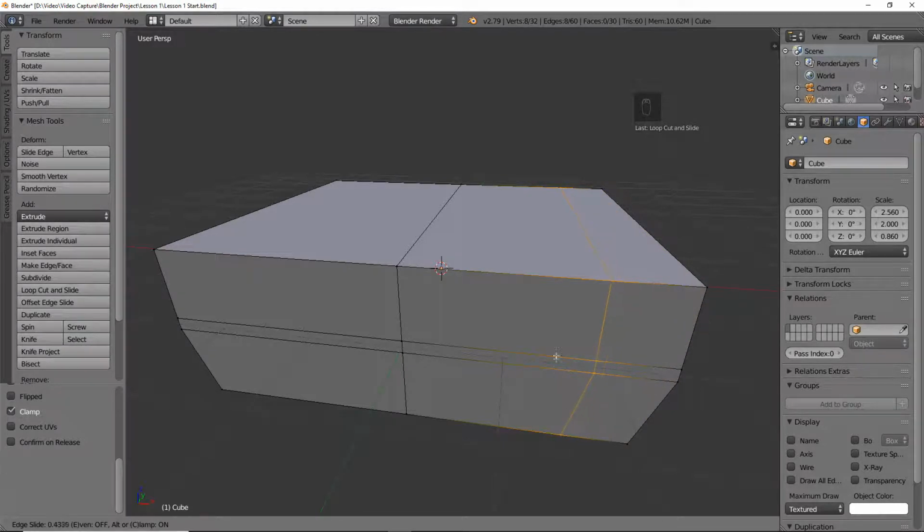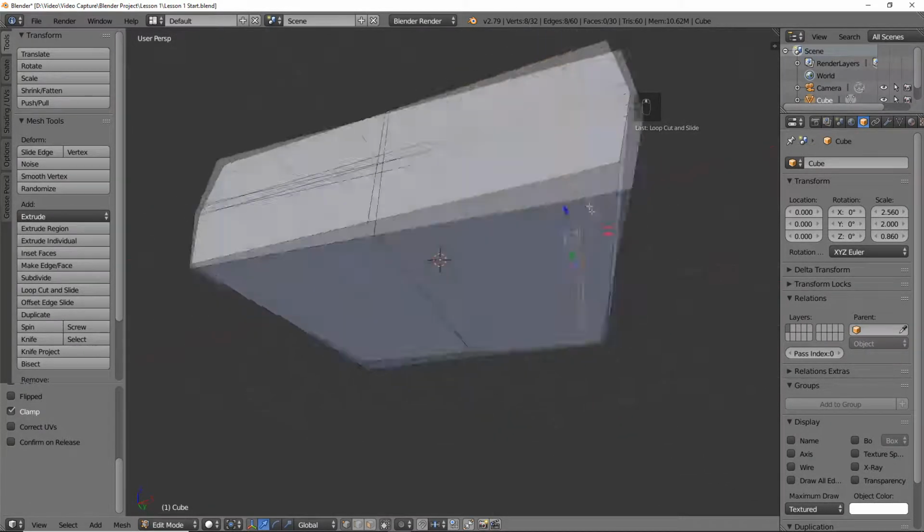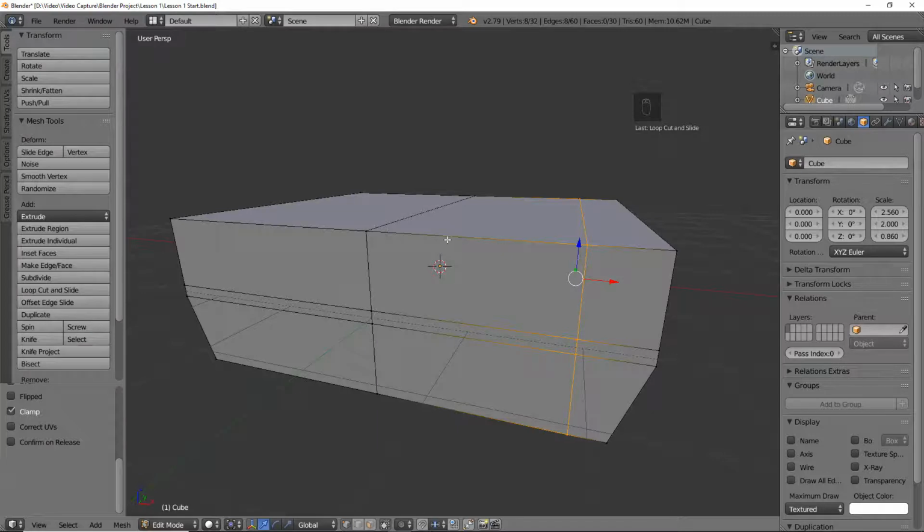So what we can do is press E, and then to take the shape of this one here, press F. Now we have a straight line we can pull all the way here and create the shape we need. Insert the next one, Ctrl R, left click and drop it right about there.